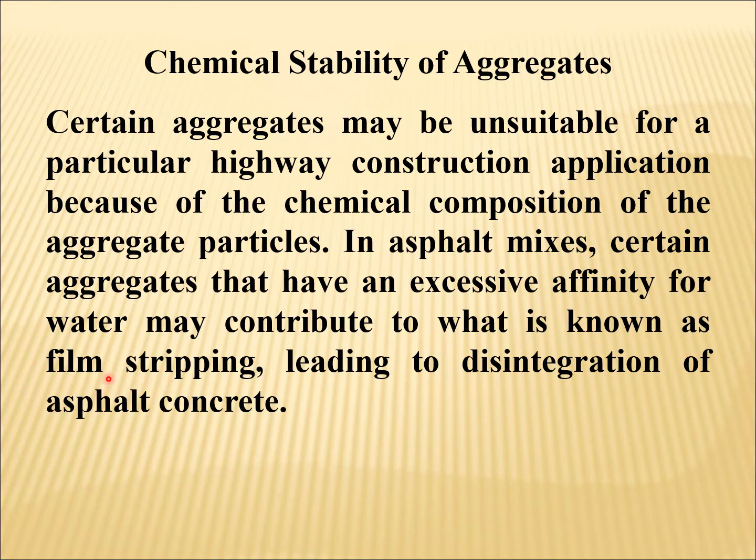In film stripping, the bond between the asphalt and the surface vanishes. This point is very important, and I will repeat that in asphalt mixes, certain aggregates that have an excessive affinity for water may contribute to film stripping, leading to disintegration of asphalt concrete.